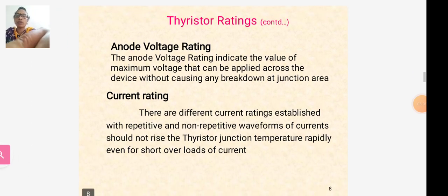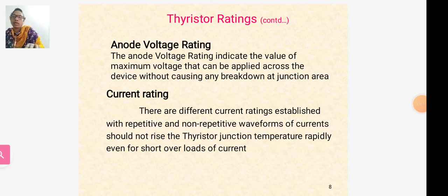First of all, we are going to discuss the anode voltage ratings. Before that, we have a few subscript notations for representing the SCR ratings. We use some letters as indicators. Capital D means the forward blocking state or off state, capital T is the on state, capital R is the reverse state, and capital F is the forward, except for the gate terminal.